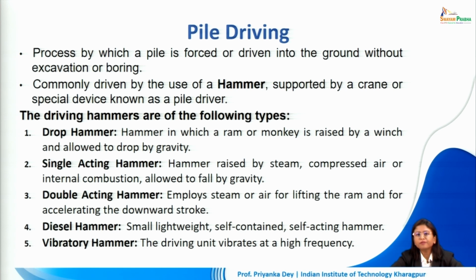The process of pile driving requires that we use a lot of force to actually drive the concrete or the precast pile into the ground, which requires us to use something called a hammer. So the drop hammer is a term which we have already seen in previous slides. This drop hammer is actually supported on a crane, and this equipment helps us drive the piles into the ground. So there are many types of driving hammers that are available to us, which we can use in construction.